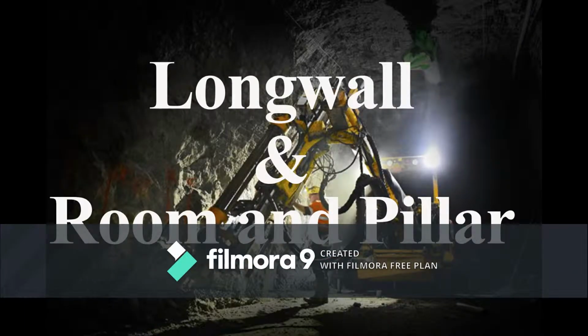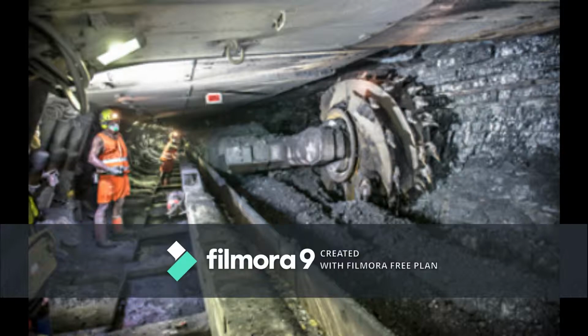Before we proceed further, one should know what longwall mining is and what room and pillar mining is. Basically, longwall mining is a highly productive underground coal mining technique. In this technique, multiple coal shearers are used, in which self-advancing hydraulic support is also installed. These massive shearers cut coal from a wall face, which falls onto a conveyor belt for removal. As a longwall miner advances along a panel, the roof behind the miner's path is allowed to collapse.